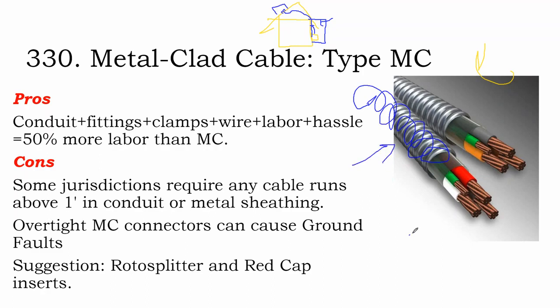So when I'm buying my MC cable, one of the things that I'm checking is, hey, even though the MC cable has a damp rating, I want to make sure that the cables inside of it are THWN, wet rated cables, so that I can put it into EMT conduit at that point for the rest of my run down to the inverter.